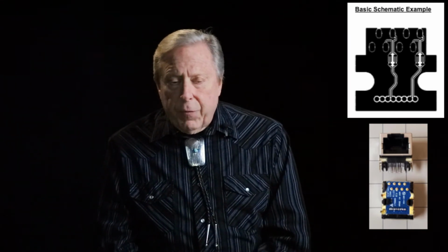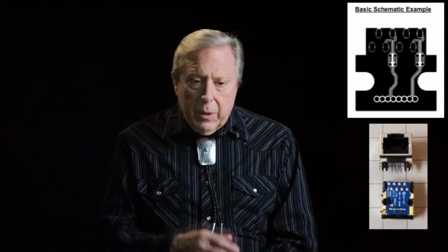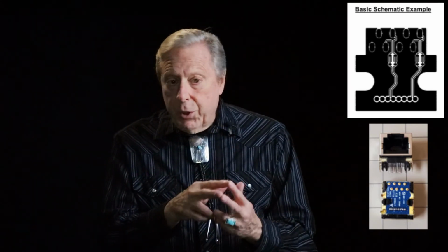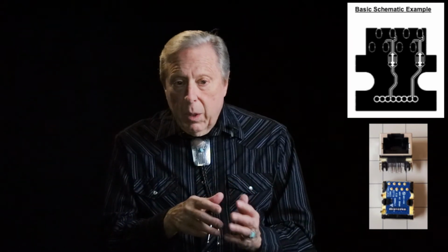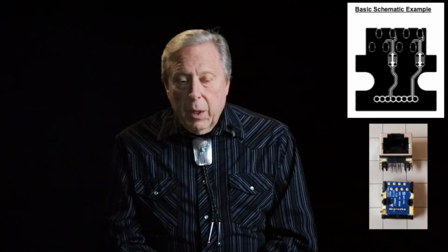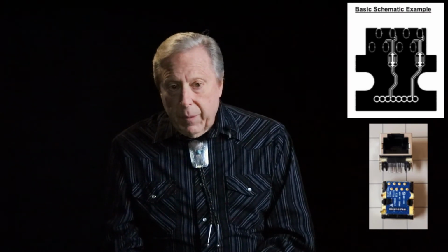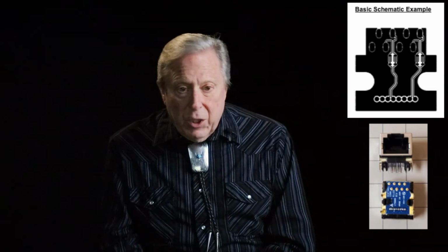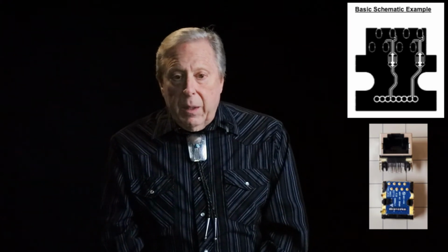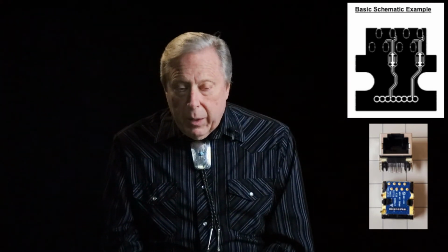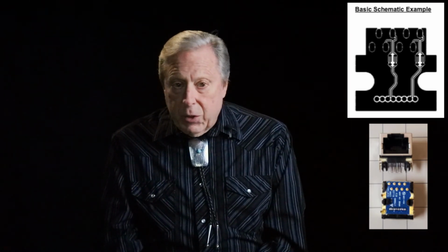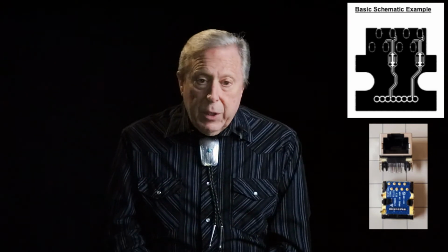What you're seeing is the differential. The difference between the differential and a split pair is really quite simple. Differential is 1, 2, 3, 4, 5, 6, 7, 8. Split pair is 1, 2, 3, 6, 4, 5, 7, 8. Now the truth is you don't need to do a split pair jack. We do have some companies that insist on it, but quite frankly, once you have the wiring put in correctly, once you have your board built correctly, a differential jack works just fine, so you can use it differentially, or you can use it in split pair.